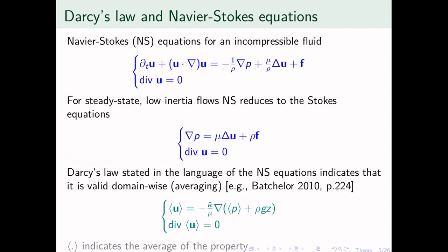For generalized flow in porous media, the governing equation is the same equation that governs the flow of all fluids, which is the Navier-Stokes equation. The full Navier-Stokes equation here for an incompressible fluid has the time derivative of the velocity field, the nonlinearity, pressure gradient, the Laplacian of the velocity field, and some body forces. For flow in porous media, we usually neglect the time derivative of velocity field and the nonlinearity, and we are left with the Stokes equation.